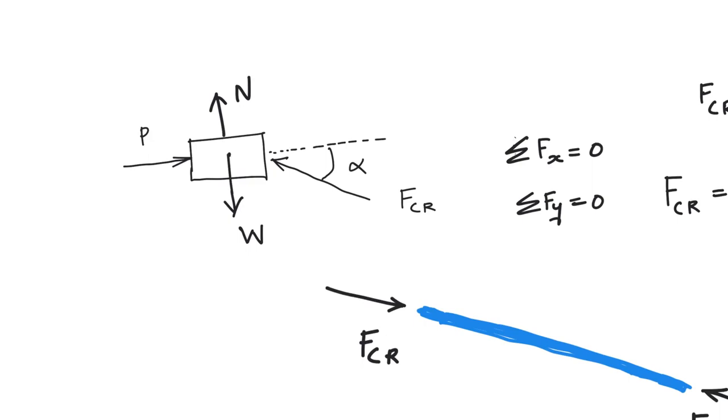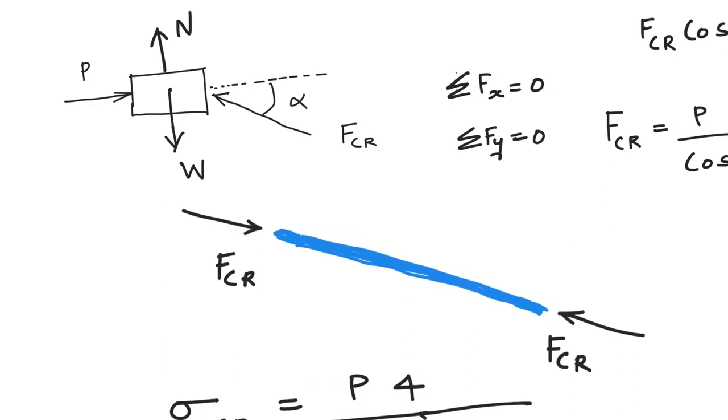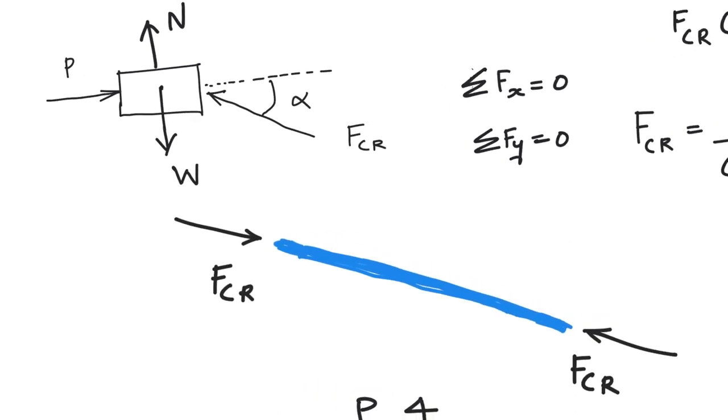Make sense? Now if I go ahead and draw the free body diagram of my connecting rod, I'm assuming that it is a two force member: there is no friction at the joints and there are no external forces acting on the connecting rod. For a two force member to be in equilibrium, the forces should act in opposite directions and be the same in magnitude.